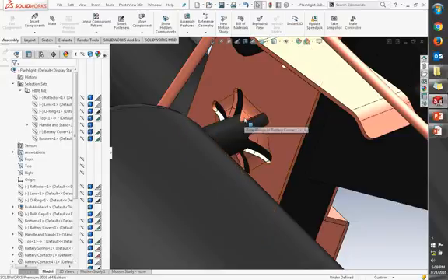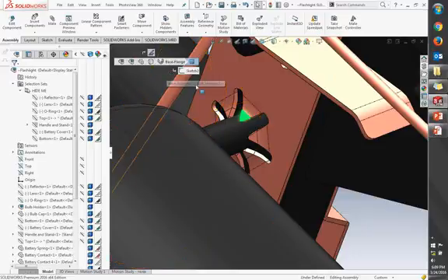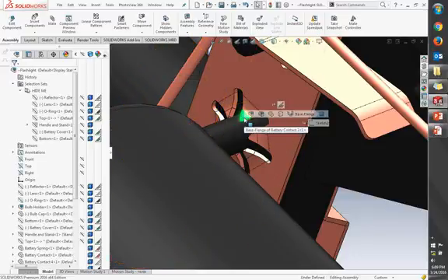So one of the things you can do is, sometimes I'm a little bit too lazy. I don't want to move my mouse all the way over here, right? So with my mouse still where I selected it, I hit the D key, and it brings that breadcrumb right next to my mouse. And that works with confirmation corners, OK, cancel, any dialogue. Hit the D key, and it brings it right to your mouse. So it's a really, really great tool.